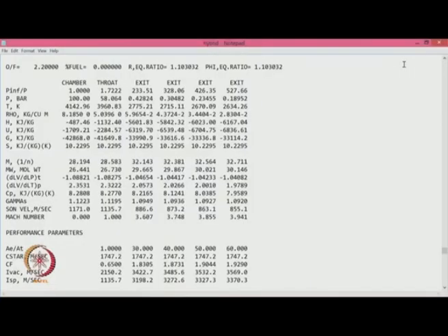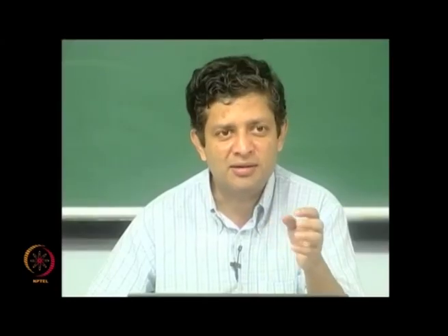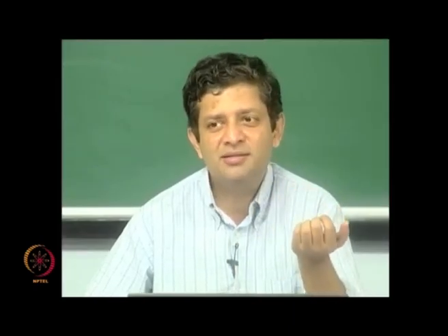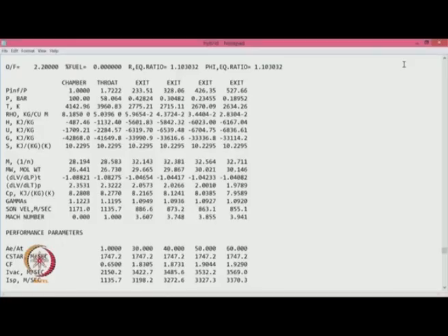Aluminum hydride is a good additive to add, because it can then increase the specific impulse, and if you look at the specific impulse with HTPB and LOX, as I said earlier, this is very similar to what you will get with kerosene LOX, but if you want to go beyond that, you have to use something like aluminum hydride, which will increase the specific impulse even further.